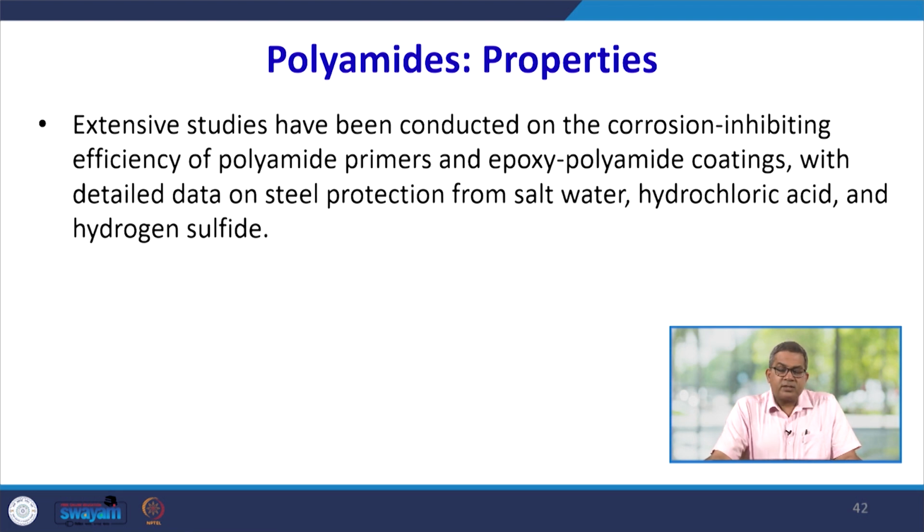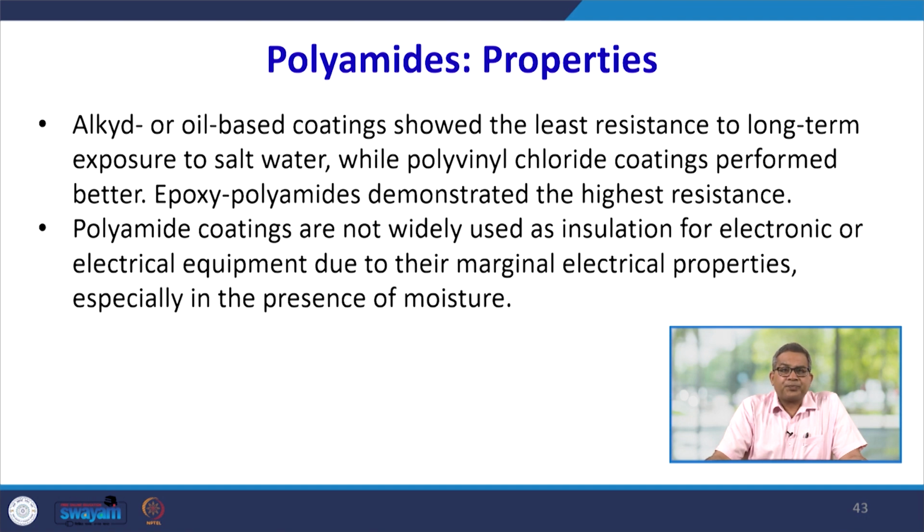Extensive studies have been carried out on the corrosion inhibiting efficiency of polyamide primers and epoxy polyamide coatings, with detailed data on steel protection from salt water, which is very important for coastal areas, then hydrochloric acid for industrial applications, then hydrogen sulfide for various refining applications. Alkyd or oil based coatings showed the least resistance to long term exposure to salt water. While polyvinyl chloride coatings performed better, epoxy polyamide demonstrated the highest resistance.